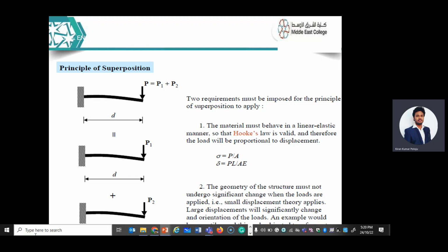It will try to resist the load which is coming. But till what time? Until it is in the elastic limit, it can resist. If I stop giving load, then this specimen is okay. If I apply load continuously, then this specimen enters into the elastic zone and plastic zone and then the yield point. So at each point, you have to note down the value, the value of change in length.